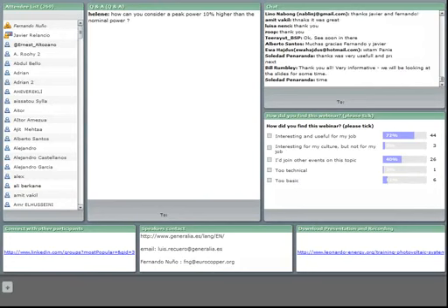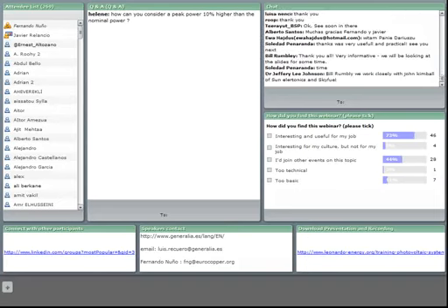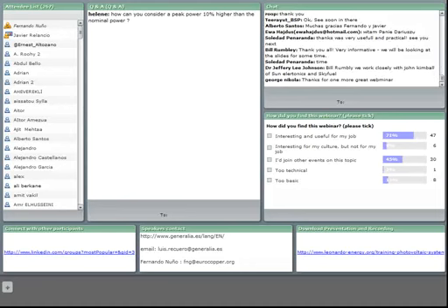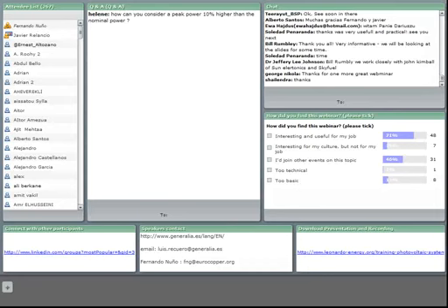Well, we have considered this in the inputs for our profitability analysis, because normally the nominal power that we are talking about is the power of the inverter. So already from the panels to the inverter, there are some system losses due to the temperature and different considerations such as the cables or even the tolerance of the panels.